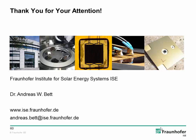But I can tell you another nice story. I didn't talk about that. We are also working on this lattice-matched material, gallium nitride arsenide. And if you do that, you find out that if you make a 6-junction solar cell, which is more complex and has 50 layers in it, the total thickness of this structure is less than a 4-junction solar cell. At the end, it's cheaper to do it. So you have to look into the details, but there are other difficulties. I mean, we have to get the high efficiencies, that's the primary goal, with low cost.